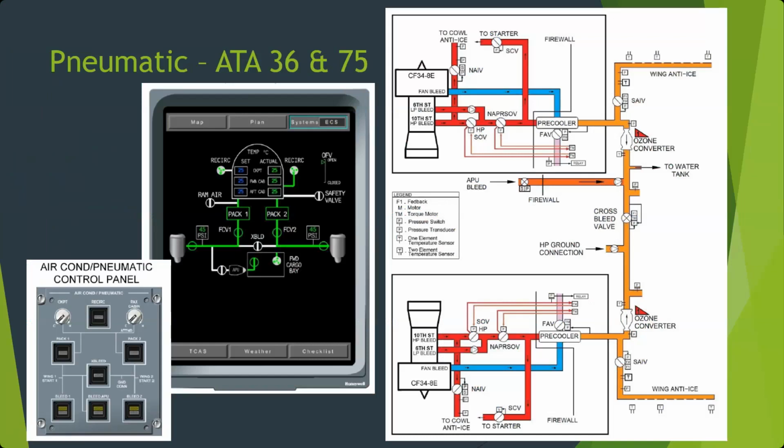And these are going to control, so bleed air 1 right here is going to control this valve. Bleed 2 is going to control the right engine shutoff valve. Bleed APU, here's our APU, it has a shutoff valve. We have a cross bleed. Normally these are operated with the manifold split, but we're going to have a cross bleed in the middle.